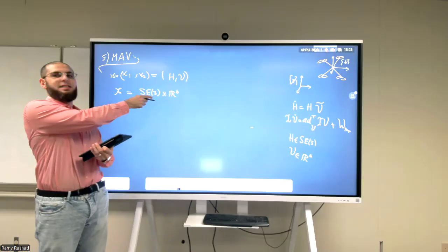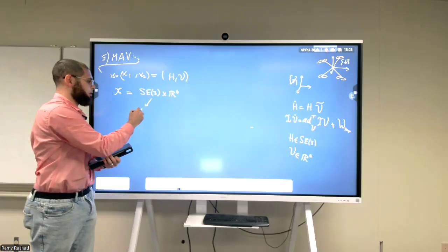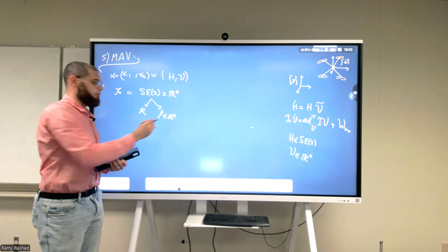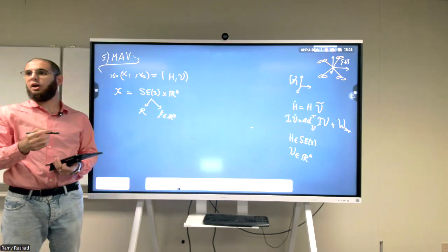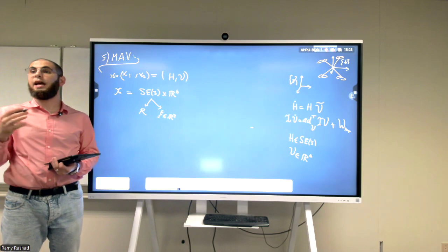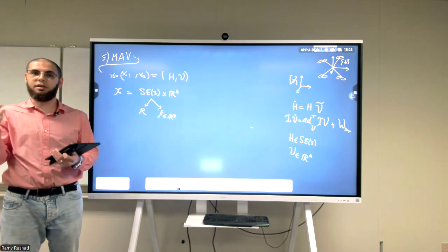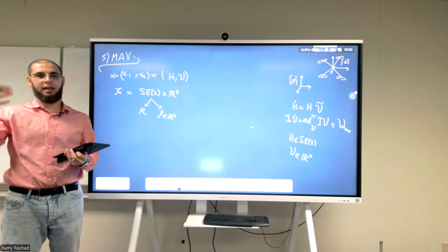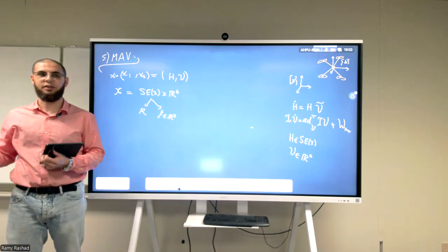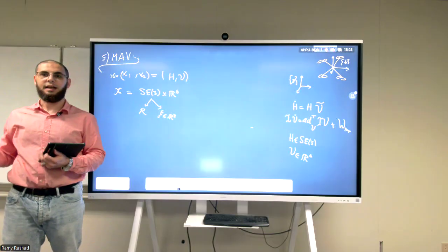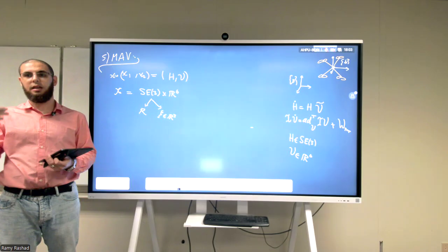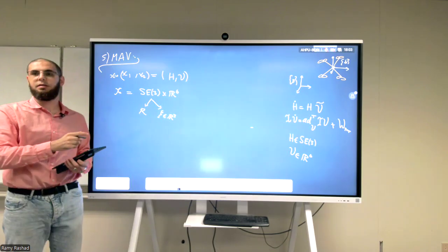You remember what SE3 had? It had the rotation matrix, and it had the psi. The psi is naturally in R3, but the rotation matrix, is it naturally in R3? But I can find 3 small numbers that represent it. What do we call them? I can give you 21 different definitions of roll, pitch, and yaw angles. I can give you 21 different ways of defining 3 numbers that locally parameterize a rotation matrix.